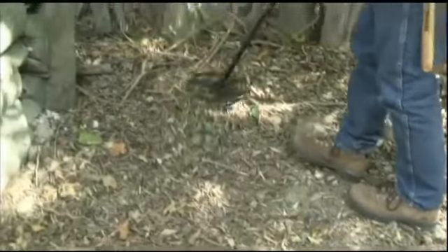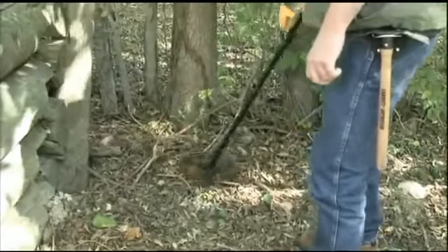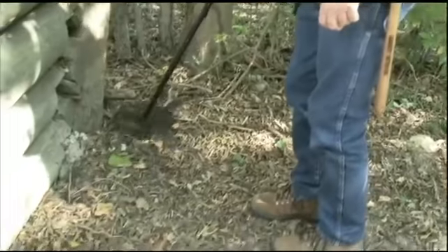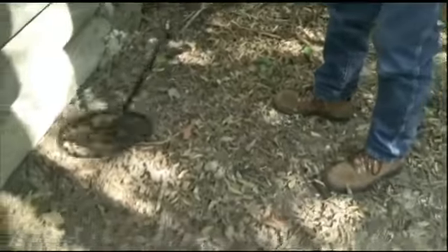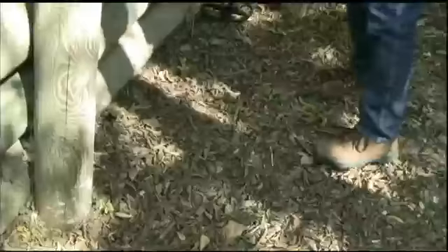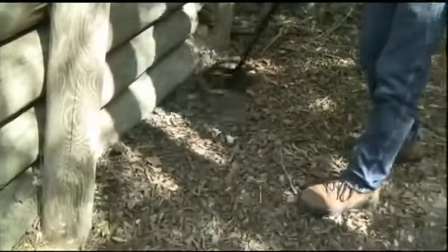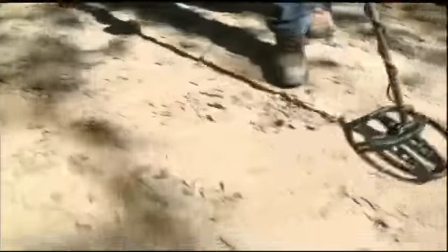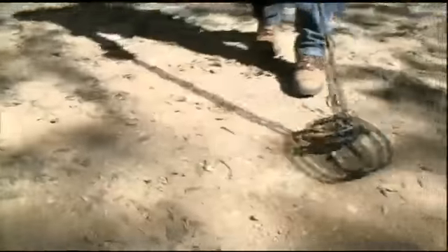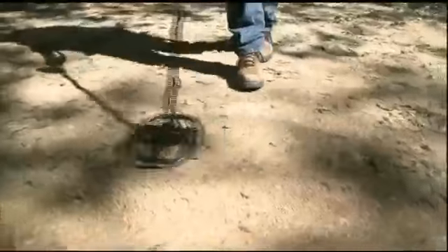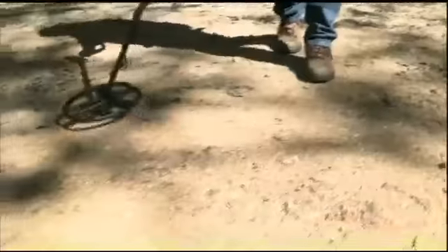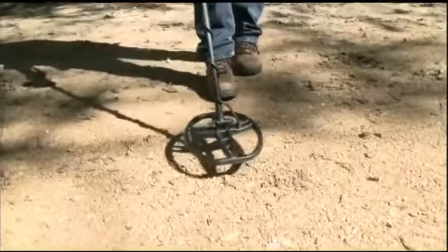3 factors can cause your detector to appear to behave erratically: outside electromagnetic interference, irregular ground mineralization, and a large number of trash targets. When such conditions occur, make certain that you are scanning with your coil at a constant height. You might find it helpful to raise the coil by a couple of inches.